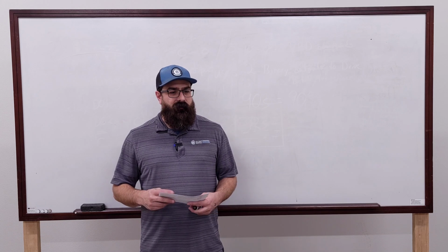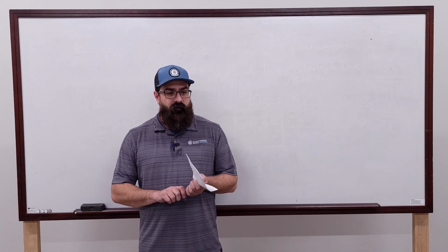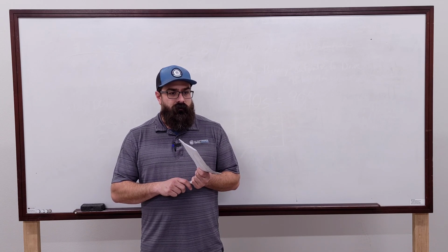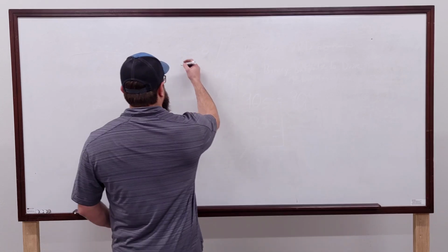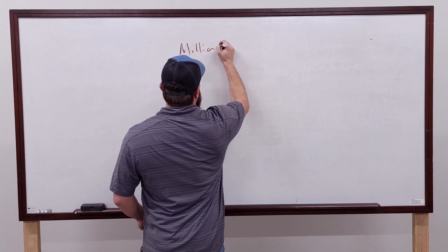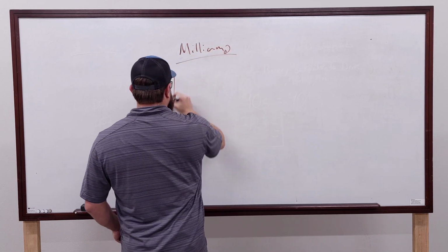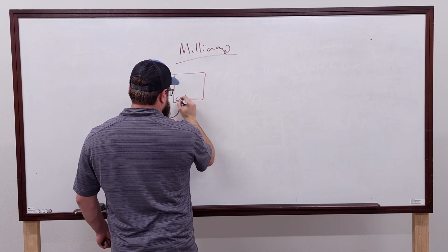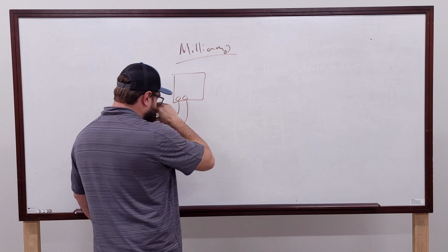You understand what I was saying about the milliamps thing with testing it? How you put a meter in series? So if you've got, this is our controller. It's got 2 terminals. You've got your wires coming in from the field.